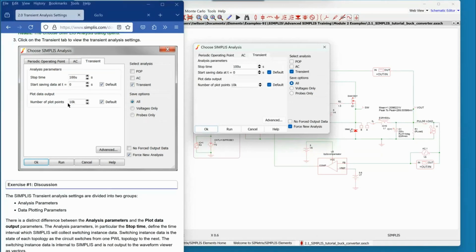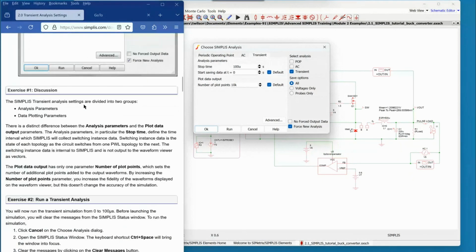I need to show what actually comes out, because the reason that we do this is some analyses like FFT, and possibly you may want to do some. You may want to export the waveforms and do some secondary analysis with some other tool. And that tool, for whatever the analysis might be, FFT is a good case in point, requires equally spaced data points. So that's why we do this. SIMPLIS actually outputs something that's this plus. And so let's look at what it is. And then if you don't mind, ask that question one more time, because it's an excellent one.